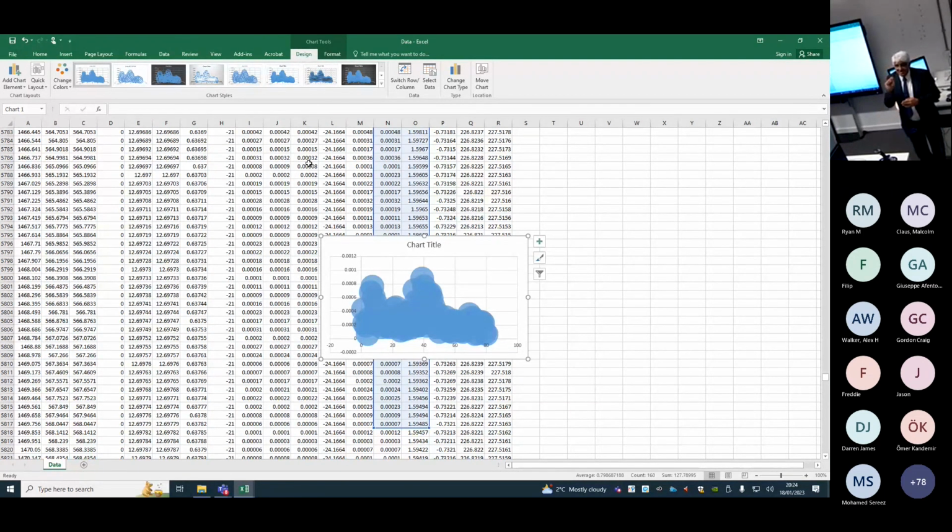As soon as the test is finished, pause it again. Note the mission time again. So when you go through the data file, you'll be able to go to the start of the mission time and end of the mission time for a particular test. And then you'll be able to access just those specific rows of data rather than the whole data file. So it's always a good idea in X-Plane to use the mission time and use the pause feature to start and stop your tests.